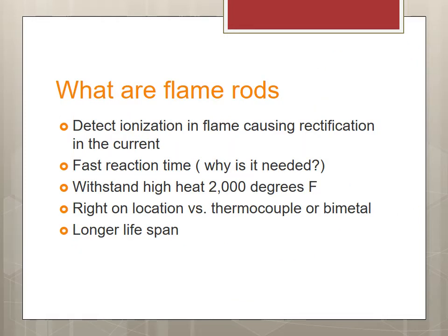What are flame rods? So we covered the types of boilers, and if you take power plant, probably you'll go in depth with types of boilers and how they are configured. But now for the flame rods, what are they? It's a new way to detect flame. They're not optical, they don't sense heat, they don't sense light, they sense ions. And a lot of you, in the first portion of the semester, we were talking about what we produce when we have fire. We have flame, we have light, and we also have ions. So this invention came about as a means to detect flame and the amount of flame as well, and that is dependent on the ions coming out of the flame.